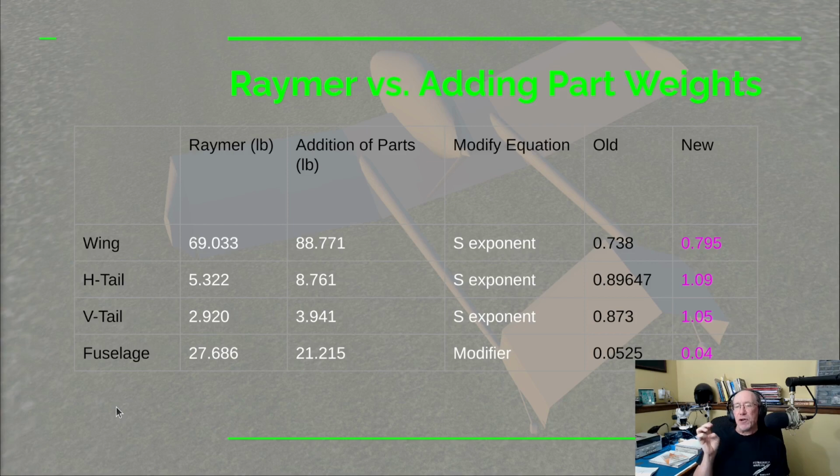The reason I say that is for an aluminum ultralight, we've got a minimum gauge problem. For our wings and our vertical tail, horizontal tail, the fuselage, in this case on the UWS-4 booms, they're going to be aluminum sheet. And the minimum gauge you can get on aluminum sheet, I shouldn't say it's absolute minimum, but typically that's 16 thousandths of an inch. I've heard you can get 12 thousandths, but it's like dealing with aluminum foil. It just bends and warps too easily. So let's just say the minimum gauge for ultralights would be 16 thousandths of an inch. No matter how thin we would like to make these skins on the airplane, we can't go below 16 thousandths.